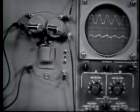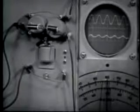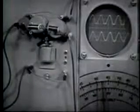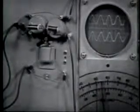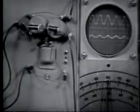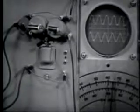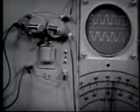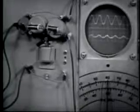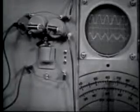Now let's check the frequency response of this circuit and see if we have indeed improved it. All right. Notice now that I only have to go down to about 550 hertz and I have maximum output from the filter. The same is true on the other side of the frequency we wish to reject. At about 650 hertz I now have maximum output from the filter. So I'm now rejecting a band of frequencies much closer to 600 hertz. I have indeed improved the frequency response of the filter.